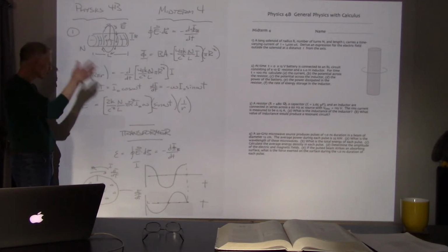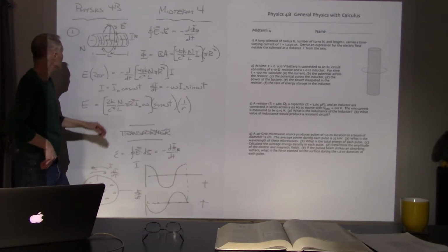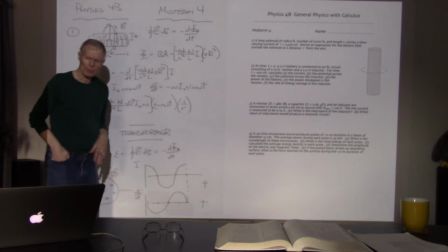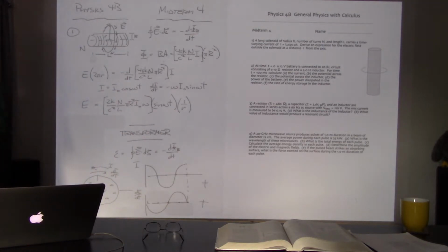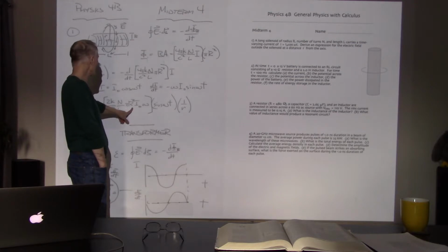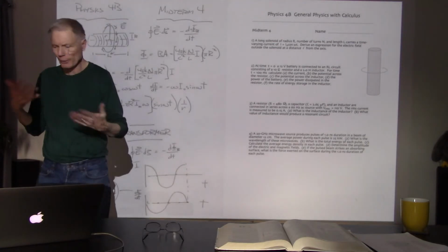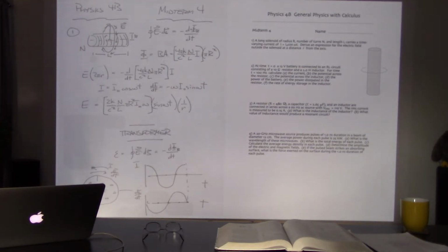And it says that the strength of the E field, and therefore the strength of the EMF, will depend on how far we are away. If we want to get the best effect, we want to get that loop pretty close in, so it's just wrapped right around the solenoid. Let's get that inside there. We'll get the full flux in that case. And then there's a factor of omega. So if I oscillate this faster at a higher frequency, that's a higher acceleration, right? Higher frequency of oscillation would be a higher acceleration. That's going to give us larger electric fields outside that region.